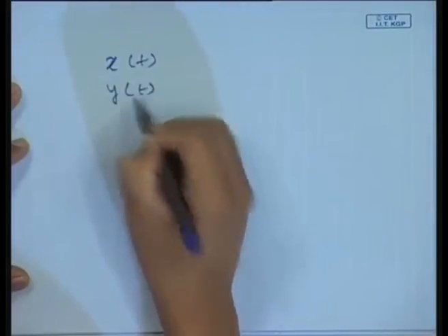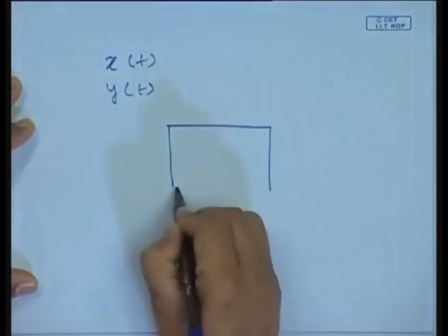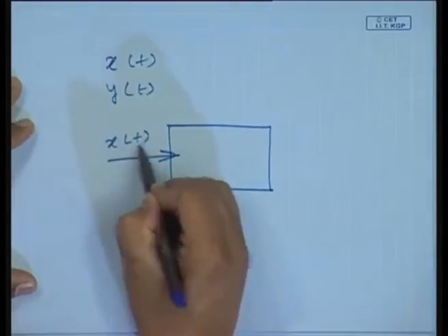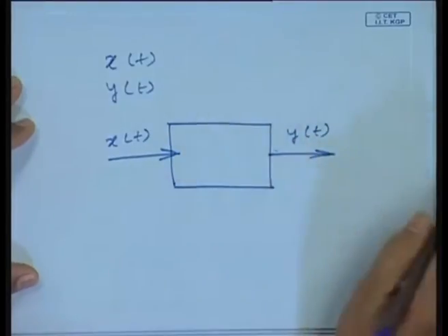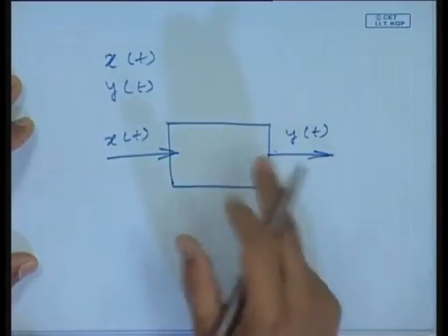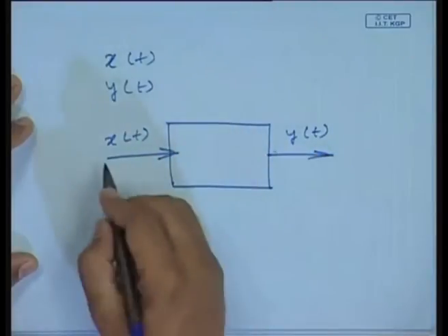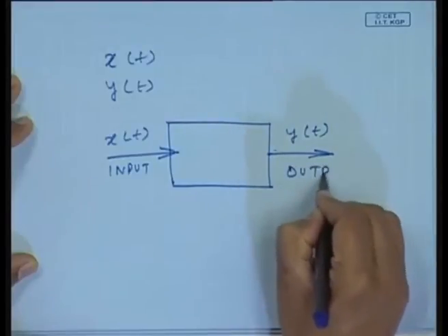Now, let us see when there are two signals, we will have what is known as the cross spectrum. Suppose I have two signals x(t) and y(t), and usually in a mechanical system this can be very easily related to an input signal x(t) and an output signal y(t), and to know the linear relationships between the signals, whether one is causing the other, to see the causal relationship between the output and input, I can look into many forms.